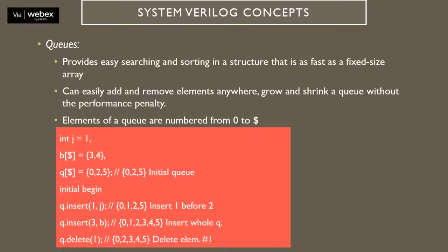If the allocated size for the queue is less, but during the operation the size of the queue keeps growing, then System Verilog itself will automatically allocate the extra space required for the operations. So if there is an ambiguity in the size or in allocating the locations for the operations, then queues are the best option.